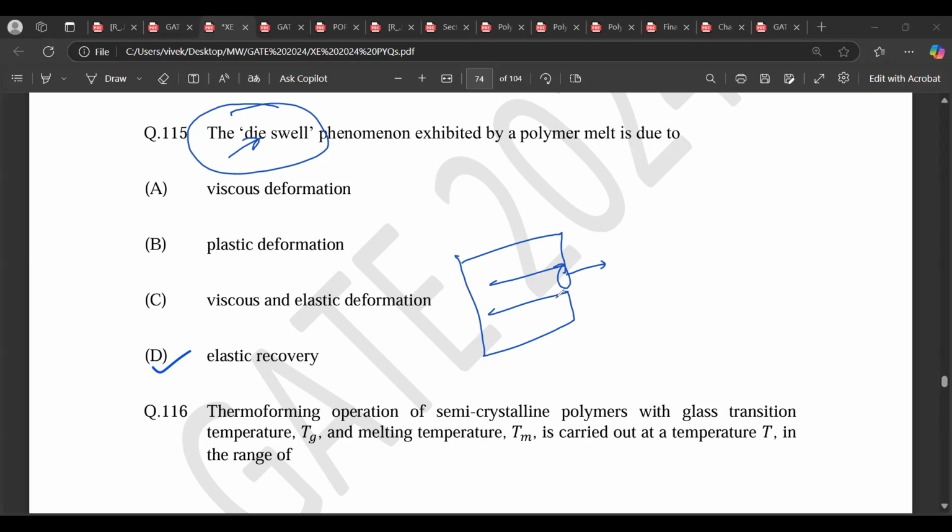If you remember the viscoelastic phenomenon, it is happening here because the polymer is somewhat semi-molten or above Tg. So it will show viscous behavior, as well as some components in solid state showing elastic behavior. Most polymers show viscoelasticity. In the viscoelastic effect, if you see the curve, you'll be able to understand the different components while giving the strain with time.